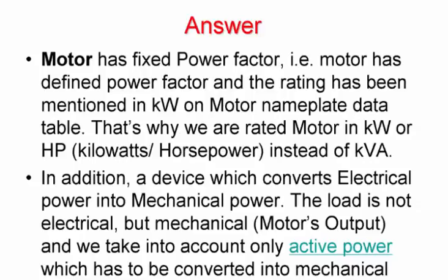And the reason for that is the motor has got a fixed power factor. So it's a defined power factor, and the rating has been mentioned in kilowatt on the motor nameplate. And that's why the motors are rated in kilowatt instead of kVA.